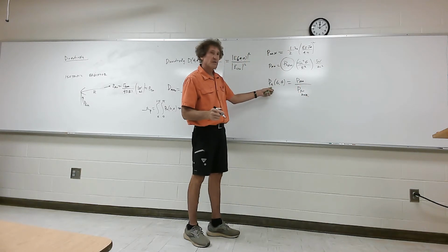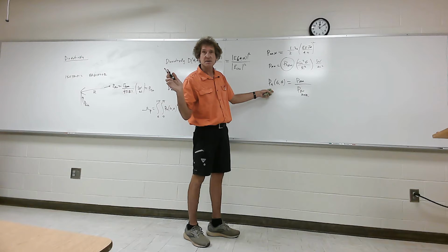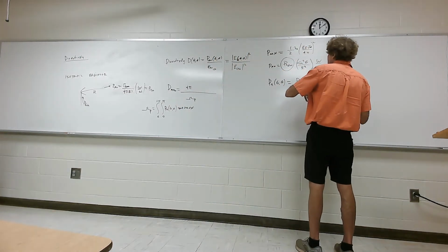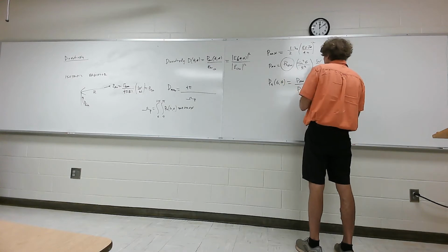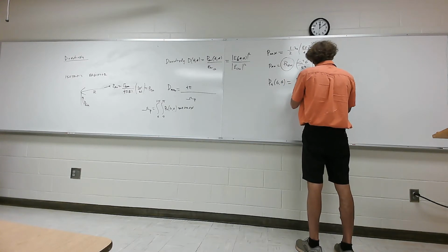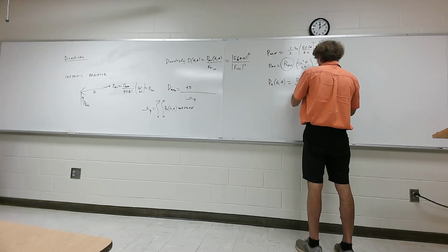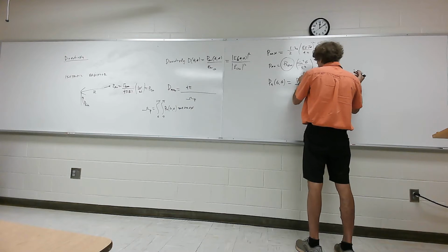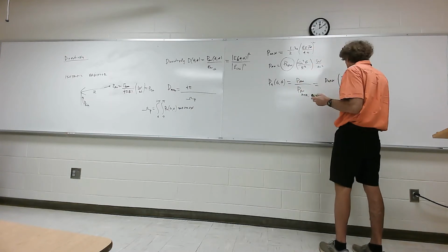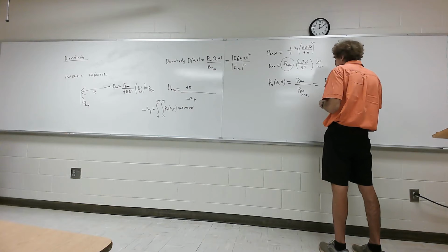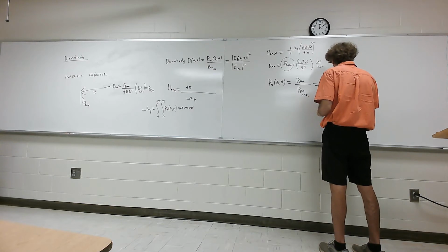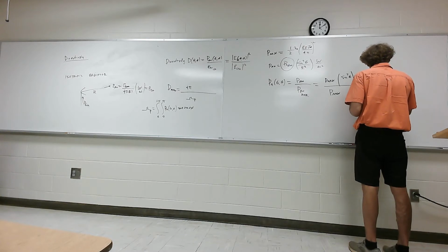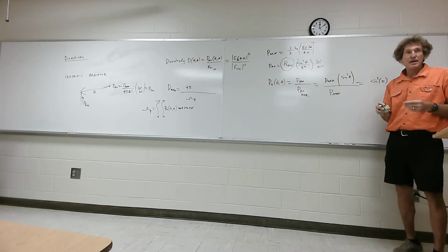So for R's right here for the short dipole, and please pay attention to this. For the short dipole, you can see that P max is right there, right? So the average power density would be P max. I made sure I broke it out. And then it's times sine squared of theta, technically over R squared, but R squared cancels all the time, so you don't even have to put it there. Over simply P max, right? So that means it's simply equal to the sine squared of theta. Does everybody follow me on that?